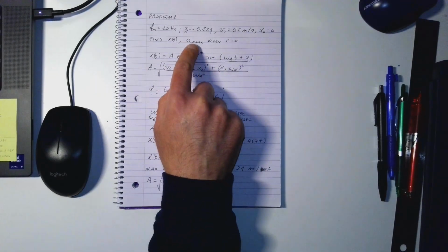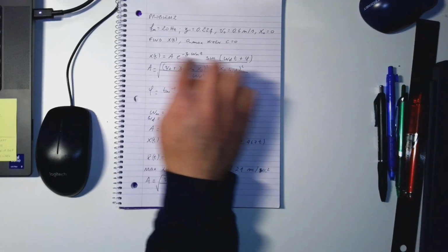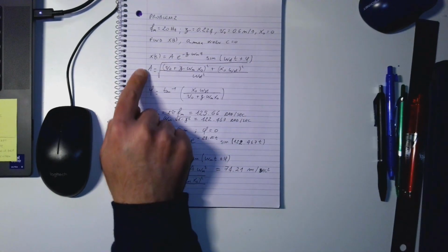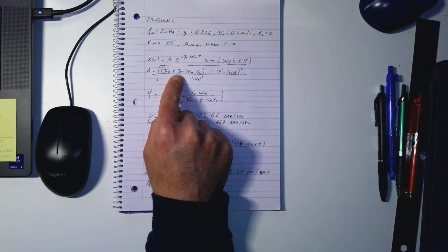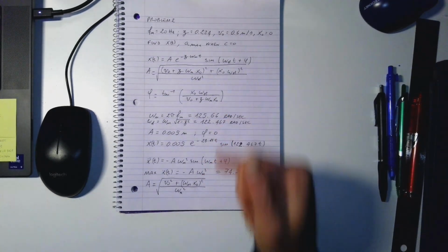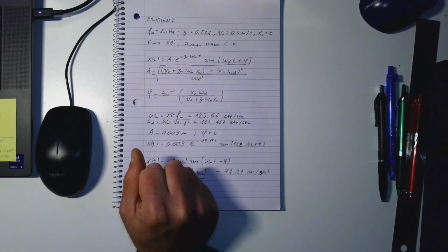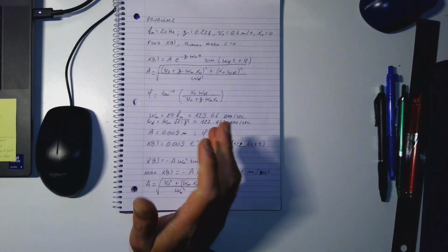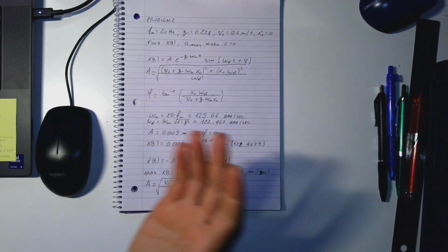In this case, we were asked to find only the amplitude, so we can look at the amplitude, or we can simply take the expression that we found for the damped system and plug in zeta equal to 0, because in this case, again, the system is undamped. The result will be exactly the same, and this lets us understand that the undamped system is simply a particular case of damped systems where zeta or c are equal to 0.